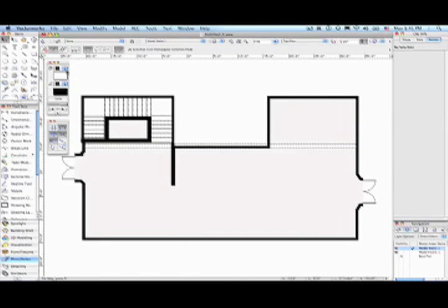Okay, this clip will show you a technique to create crown molding using an existing edge in a model. I'll take a network of walls and use the extract tool from the 3D modeling tool palette to create the path, and I'll use an image downloaded from the web as the basis for the molding profile. The profile and the path will be combined using the extrude along path command from the model menu.